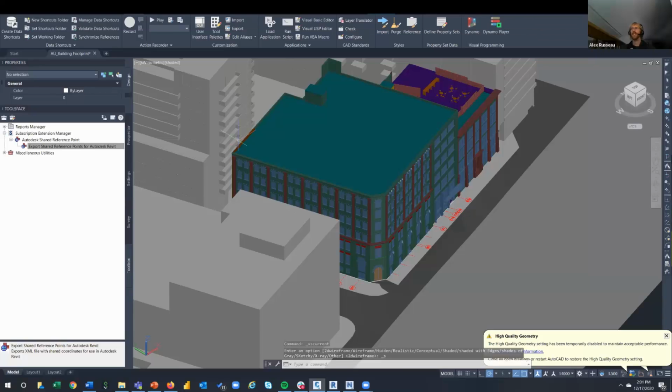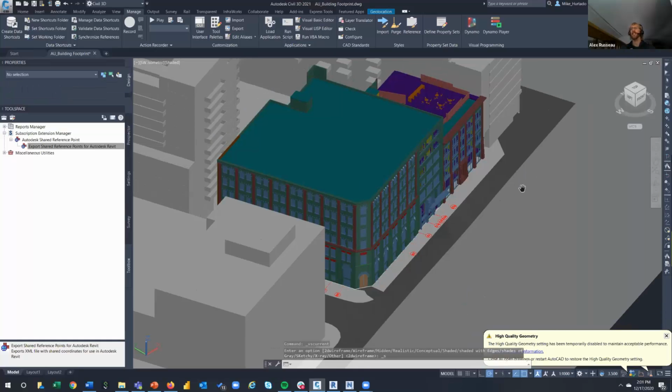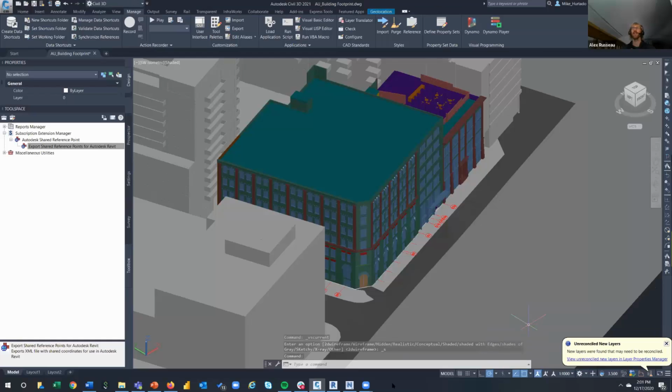There was one question that came out talking about the architectural model being done well in advance of civil. That's always the case. It pretty much always is, so it's not a worry. Continue working. In that instance, you would use origin to link all your models around, but then you can always set up the shared coordinates afterwards. So using the site model or using that SharePoint tool, both will work at the end.